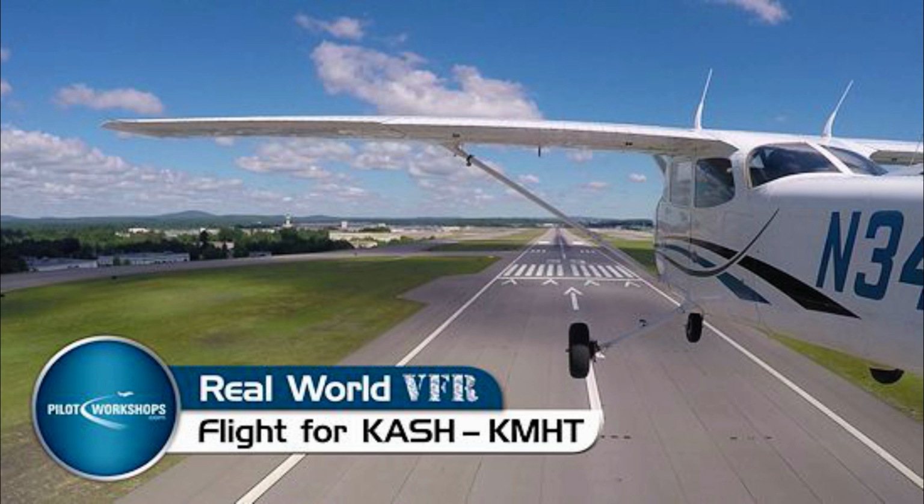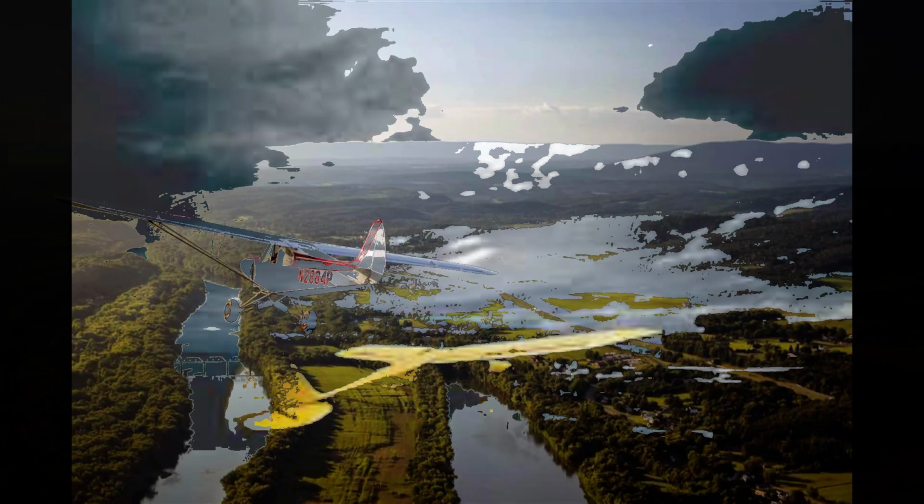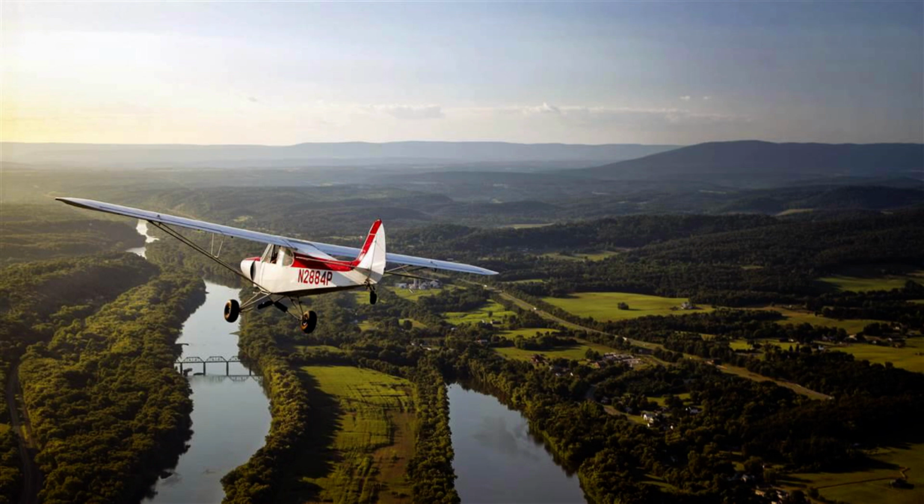However, departing VFR with the intent of receiving an IFR clearance in the air can also present serious hazards worth considering. A VFR departure dramatically changes the takeoff responsibilities for you and for ATC. Upon receiving clearance for a VFR departure, you are cleared to depart. However, you must maintain separation between yourself and other traffic. You are also responsible for maintaining terrain and obstruction clearance, as well as remaining in VFR weather conditions. You cannot fly in IMC without first receiving your IFR clearance.